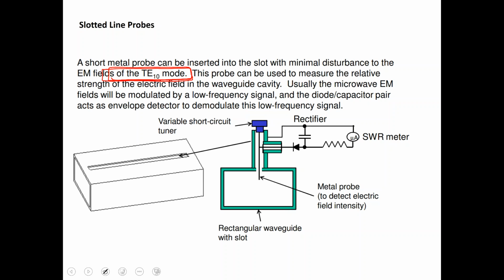We can have an electromagnetic field generated somewhere else at a high frequency, and come up with a slotted probe and add another, low frequency to it, to impose a small perturbation on the high frequency electromagnetic wave going through, and we can pick that up further down the waveguide.